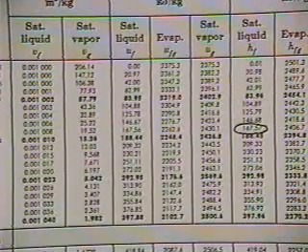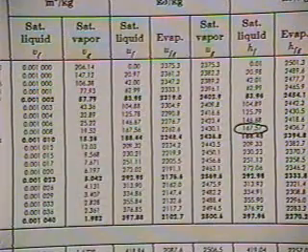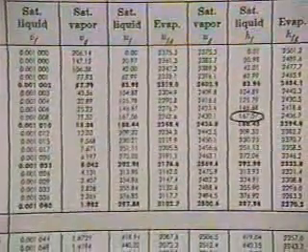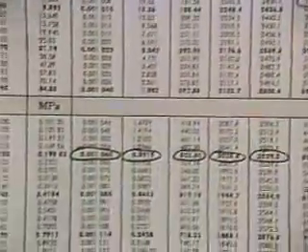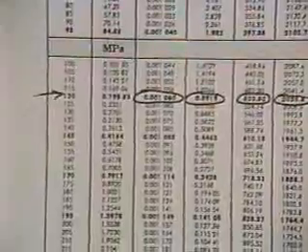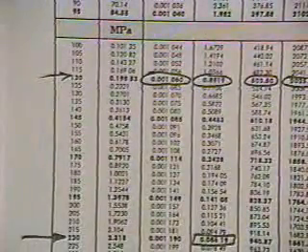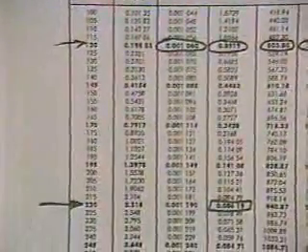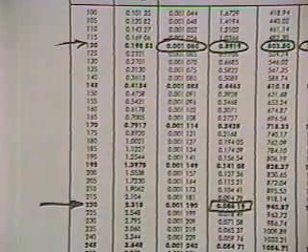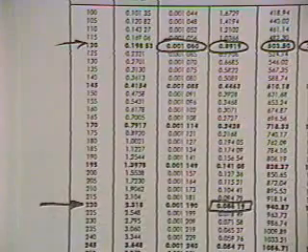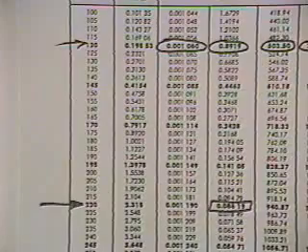Okay, we also can find state 2, and state 2 we know we've got saturated vapor at 1 megapascal. And so now let's go down to our tables till we come to a pressure of 1 megapascal. If you notice on your tables, this is a temperature table, not a pressure table. Some of the thermodynamic tables will also provide temperature data as well as pressure data.